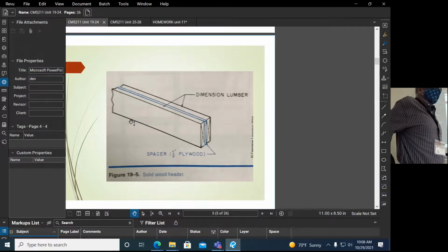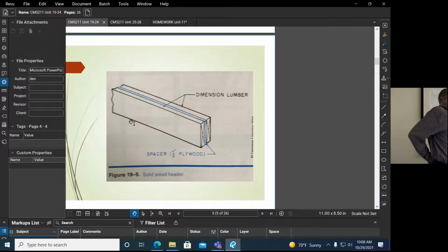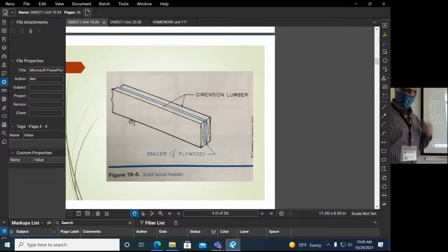Is the plywood added in there so it bends? Yeah, so to make the header stronger, they'll typically also glue it on both sides with construction adhesive, as well as nail it in a pretty 6-inch on center nailing pattern. So that header is like one piece of wood. That's the purpose of the plywood, getting the extra width. Because if you just had 2 boards sitting there without that plywood in the middle, they could actually structurally flex, but this puts it all together, makes it like a little mini beam, and makes a stronger member.